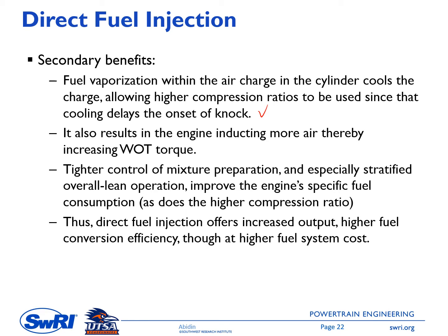It also results in the engine inducting more air, thereby increasing wide open throttle torque. This idea is similar to using a turbocharger. In this case, we have a lower temperature of the mixture, which results in higher mixture density and thus more trapped mass.